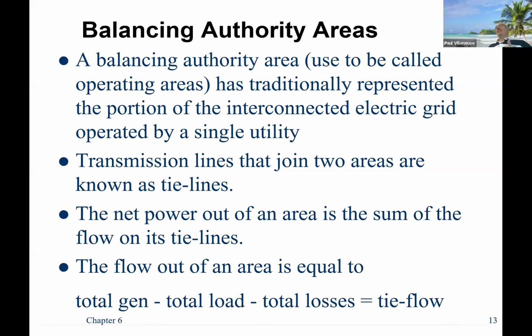They have these T lines and they monitor the transmission lines, and they actually will automatically adjust the power. If it's contractually agreed to, then no problem. If it's not, ISO New England might say, well, we're going to start monkeying with voltages here, so you can't get the power that you want. And if New York ISO still tries to force the power, then ISO New England says, we're going to open the breaker. We'll just isolate from you. So that's pretty extreme.